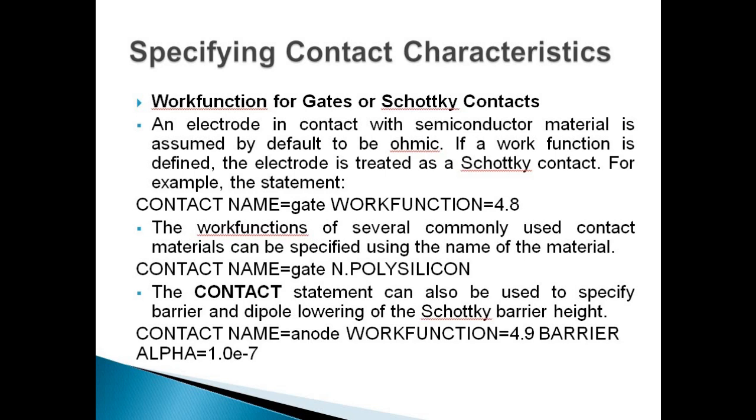One most important thing: when a Schottky barrier is defined at a contact, we recommend that a fine mesh in Y is present. This allows the Schottky depletion region to be accurately modeled. Next slide please.